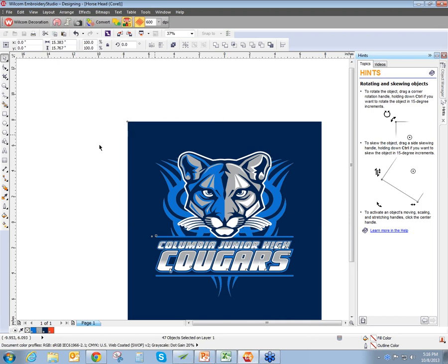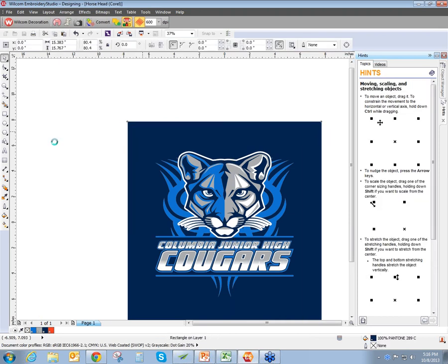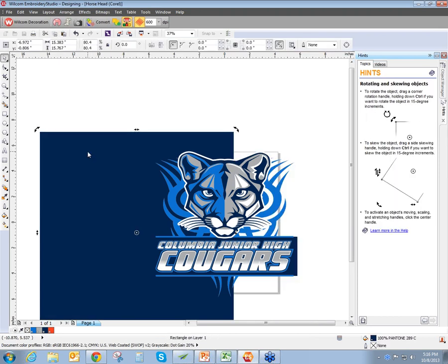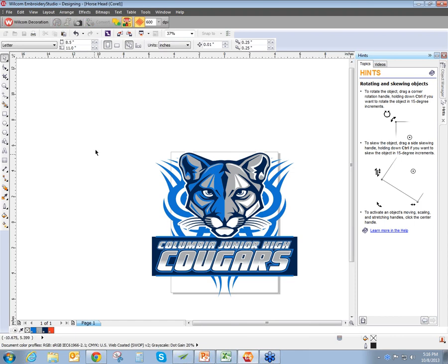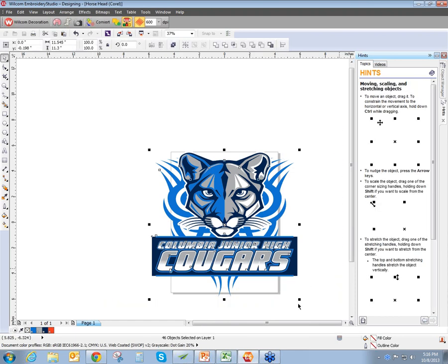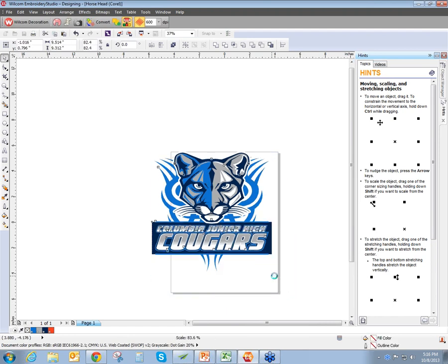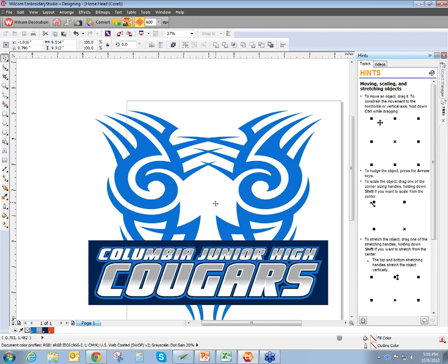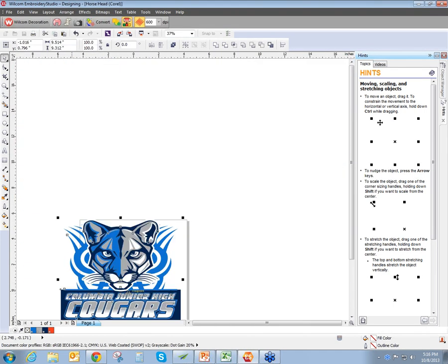So that I now can have that individual control. So my blue background, we're going to go ahead and delete that because I don't want to show the layers. Again, for demo purposes, I'm going to go ahead and keep the lettering, but keep in mind, anytime you get pictures, logos, things of this sort, it's not necessarily created, quote unquote, with a true font. You know, it's objects, it's pictures. If you can utilize the Wilcom font first, I would definitely do that, because this isn't going to convert over as we would want it.